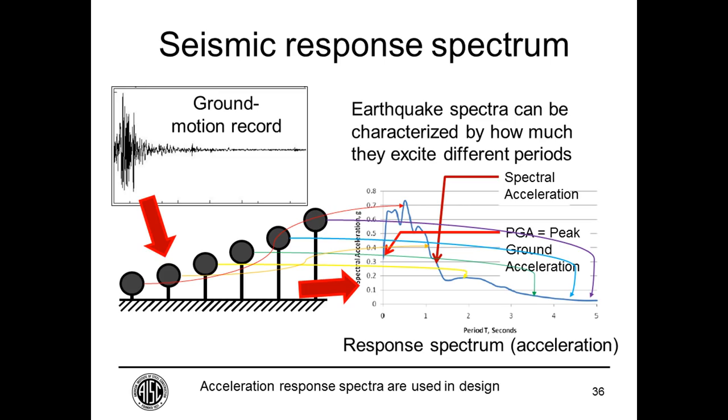Now when we go to an earthquake ground motion, mathematically we could deconstruct that complicated motion into frequency content, essentially as an accumulation or assembly of many different sine waves of different periods and different amplitudes.